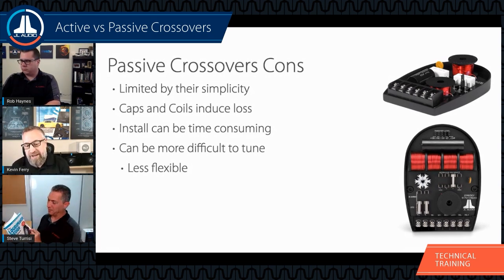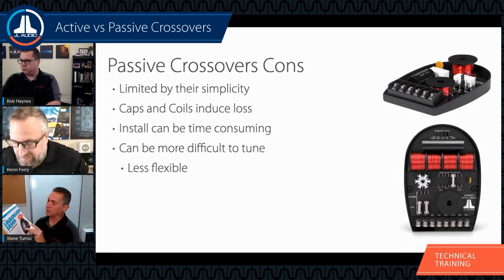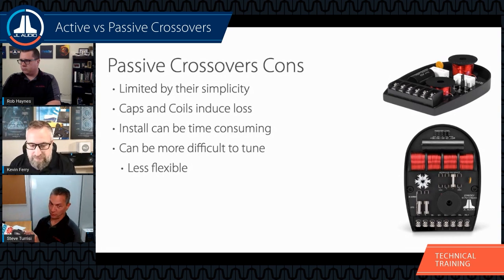You have a 30 watt and a 60 watt amplified output running active that is going to clip at the same level as one 170 watt amplifier with a passive crossover network. That came right from this book here, the Loudspeaker Design Cookbook, the 6th edition. And there's a section on page 152, active crossover networks.